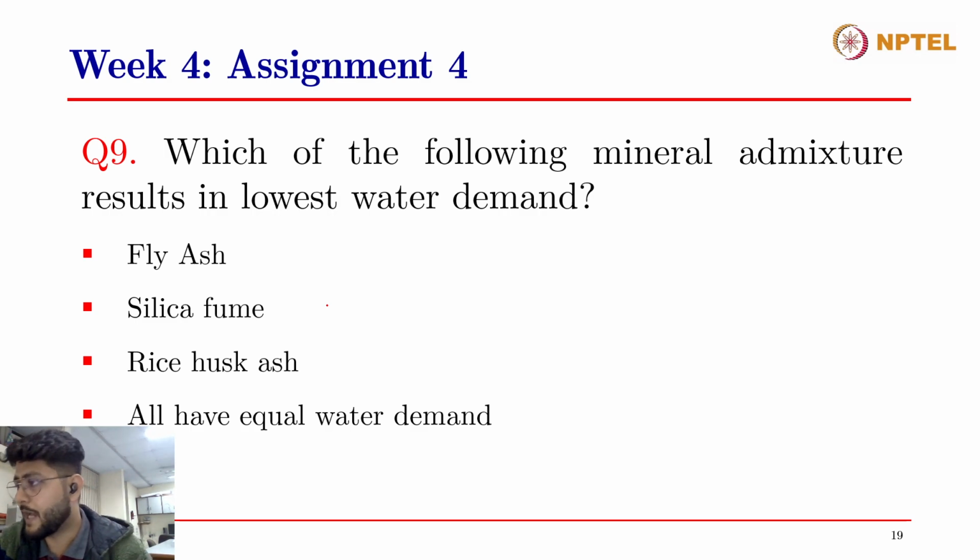In order to produce high strength concretes of, let us say, 100 or 200 megapascals or so, it is essential to use silica fume, because without silica fume you won't have such fine materials in your mix, and therefore you won't have reduced pore size and pore volume, and you won't achieve such high strength. So you need to introduce silica fume to the concretes. But in the case of high strength and high performance concretes, the silica fume ranges around 5 to 10% or a maximum of 15%, but not beyond that.